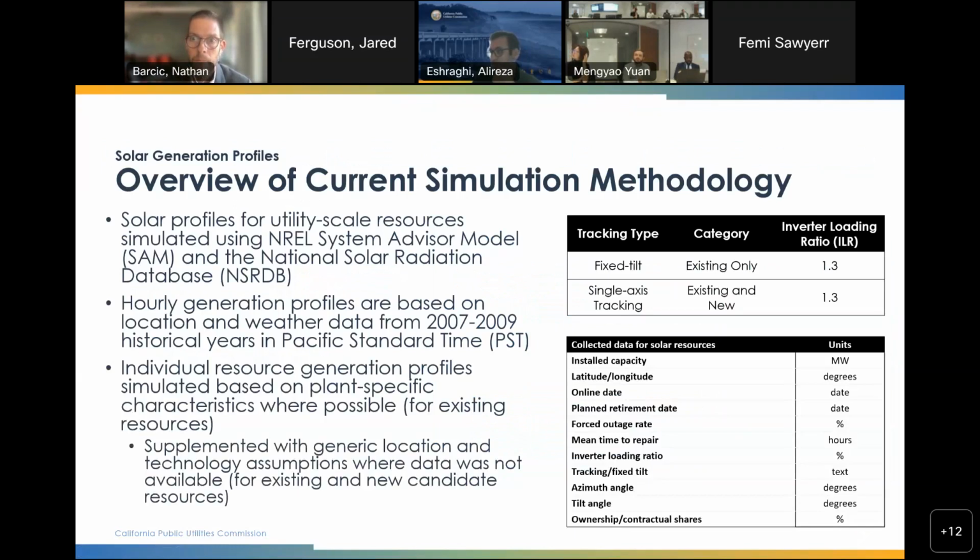So in order to get those simulated profiles, it requires a set of input assumptions for each of those different points that I had mentioned from the process two slides ago. So when you think about what the actual resulting hourly profile would be for any given simulated profile, whether it's wind or solar, it would require you to make these assumptions based on the configuration of a hypothetical or actual renewable generation technology at a given location.